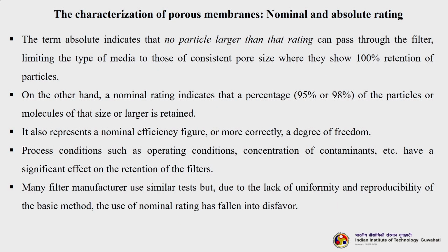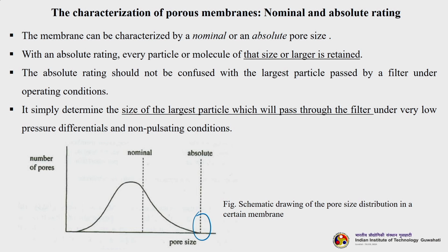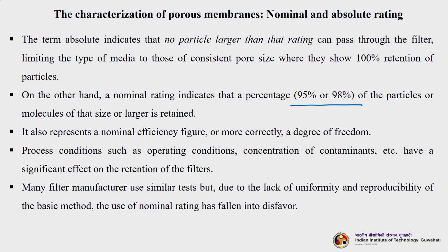The absolute rating indicates that no particle larger than the rating can pass through the filter, limiting the type of media to those of consistent pore size, which show 100% retention of particles. On the other hand, a nominal rating indicates that a percentage, usually 95 to 98%, of the particles or molecules of that size or larger is retained. So, whenever I am talking about a nominal size, you understand that 95 to 98% of the solutes will be retained with respect to this particular size.